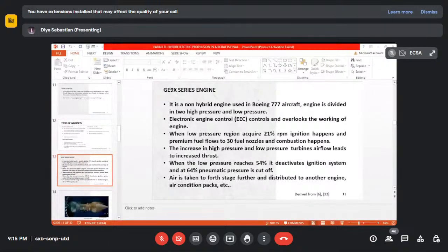Here we could see two generators, generator A and generator B. Generator A is basically controlling the working of the Rotax 915 IS engine, and generator B is charging the battery. Now the block diagram shows the off stage of the battery. Okay, and let us consider a case where generator A fails, and generator B takes control over the working of the engine.